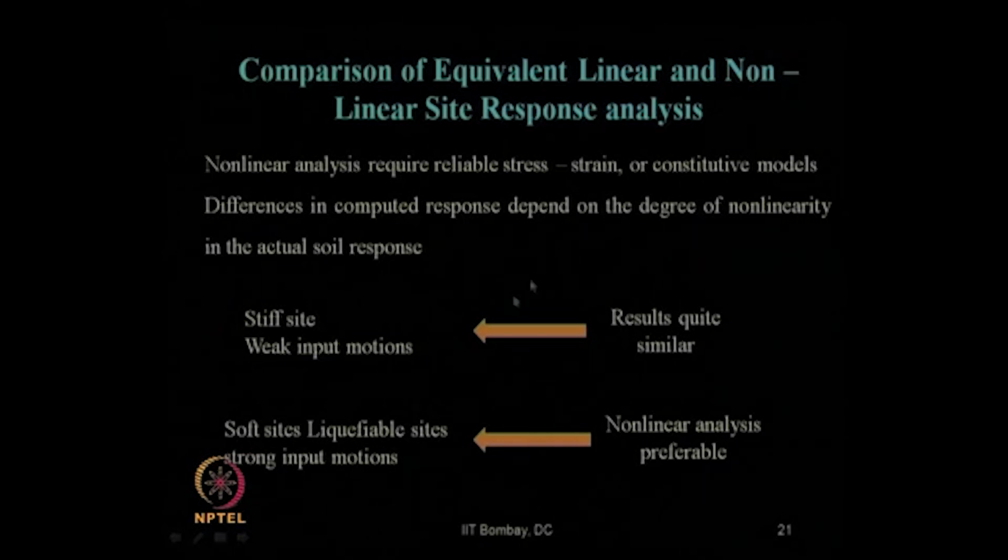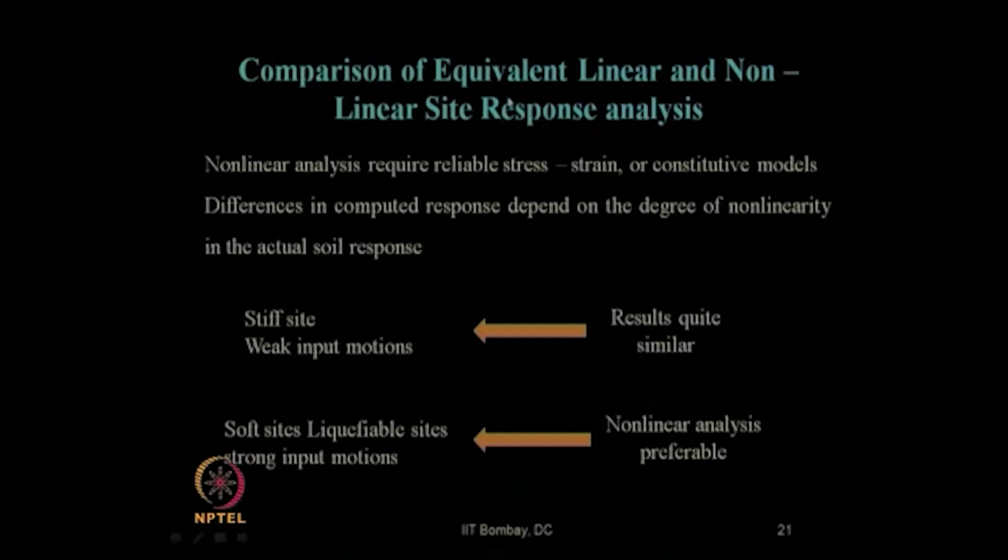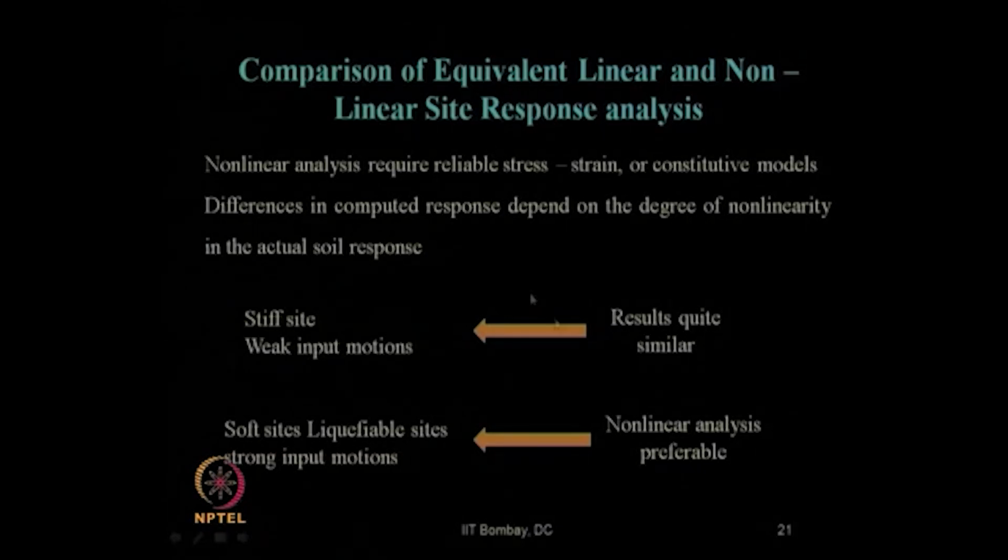That is, for a stiff soil site subjected to weak input earthquake motion, you can use either equivalent linear or nonlinear. In both cases, similar results you will get. So, obviously, it is better to use equivalent linear, which is less time consuming and simpler to analyze.